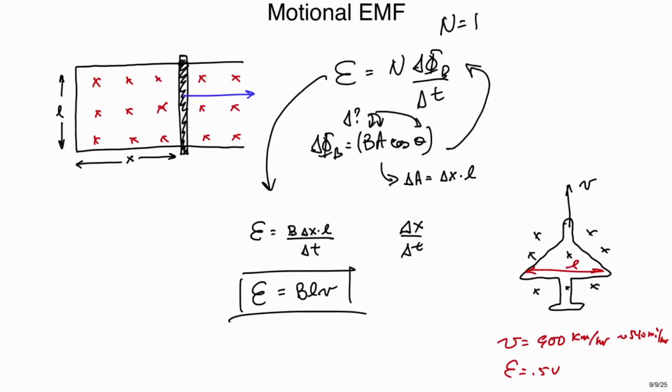So with no current flowing in here, what's my magnetic field? Zero. From the solenoid, there's no magnetic field coming from the solenoid. We're going to generate magnetic field in this solenoid. As soon as I hit the switch, we're going to go from no magnetic field to a lot of magnetic field because we're just hooked up to 120 volts and probably draw about 8 amps or so, okay?